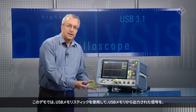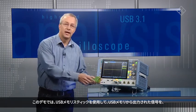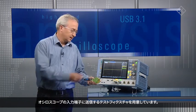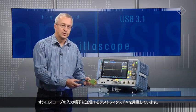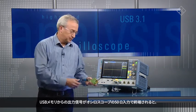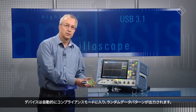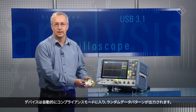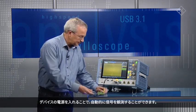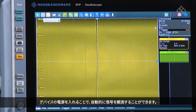For demo purposes, I'm going to use this USB memory stick, and we have a test fixture that connects the transmit signals of the memory stick to the inputs of the oscilloscope. When these signals are terminated by the 50 ohm inputs of the oscilloscope, the device will automatically go into a compliance mode and send a pseudo-random data pattern. I will power up this device, and you can see you automatically have the signals.